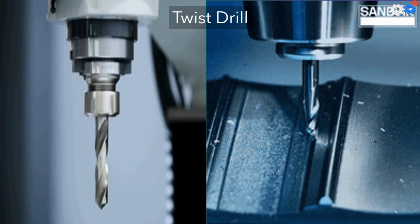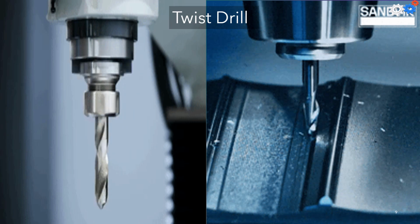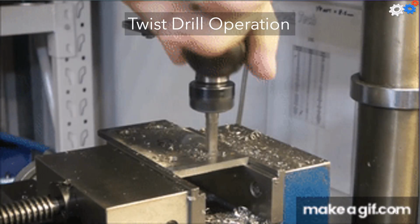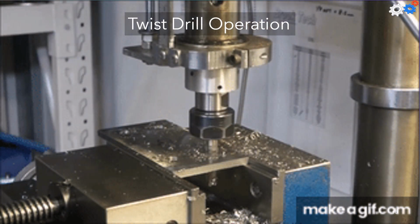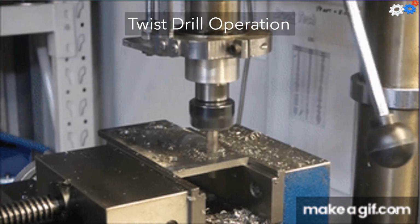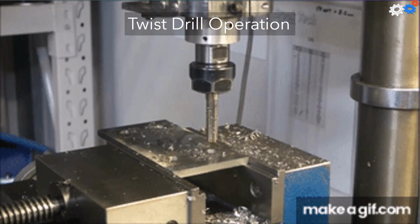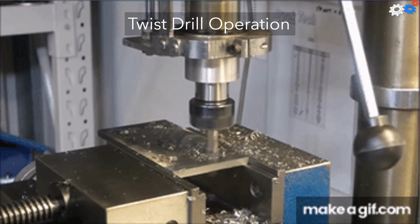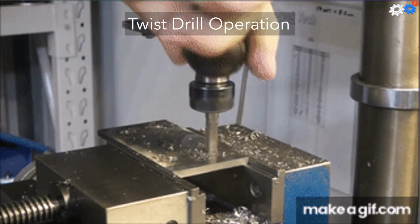The most common tool for hole making is the twist drill. Usually, they are made of high-speed steel. Shown below is a standard twist drill geometry. Rotation and feeding of the drill bit result in a relative motion between the cutting edges and the work material to form the chip. The cutting speed varies along the cutting edges as a function of the distance from the axis of rotation.